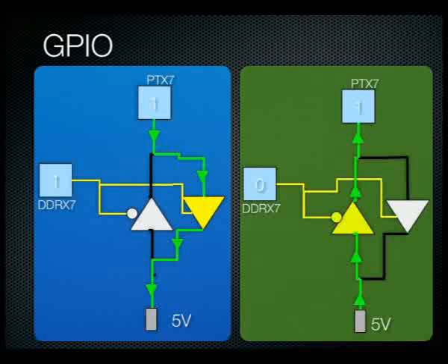Therefore any value we write in the data register in that bit location of 7 will simply be echoed out of that particular pin. Same thing in the green example, when we put a 0 in there, then effectively we make it an input pin. So whatever we echo on the particular physical pin will in fact be reflected inside the data register as a logical value.